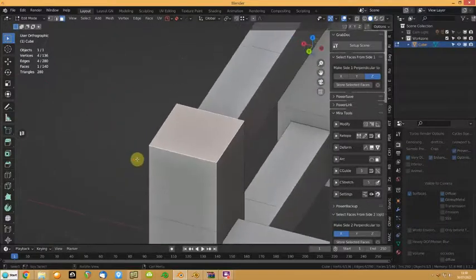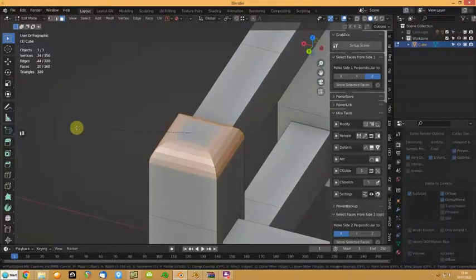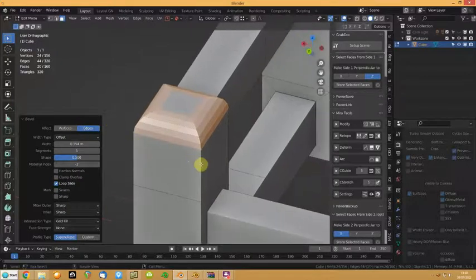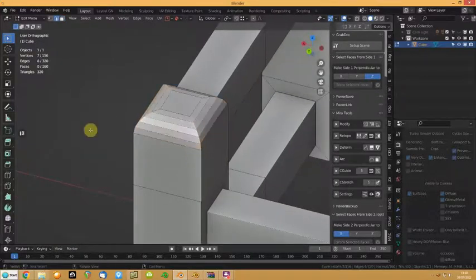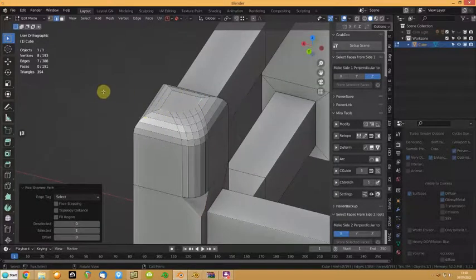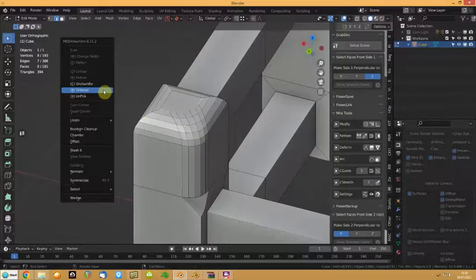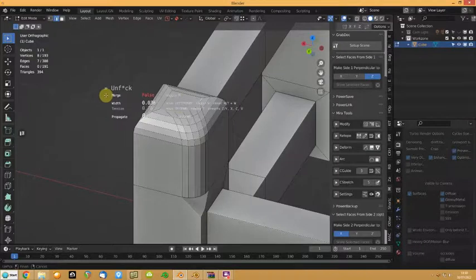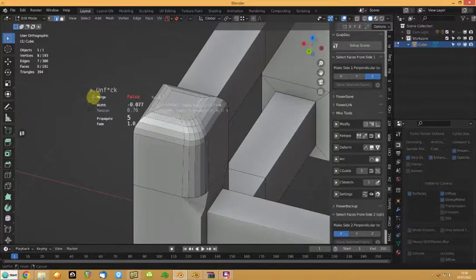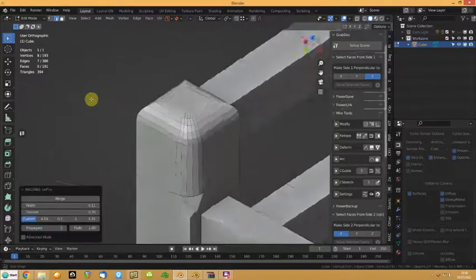Mesh Machine also has some wonderful bevel related actions. So like if we just select this, bevel it like that, and then I decide I don't like that, select that edge, control click that edge, go Y for Mesh Machine and choose that, and I can pull that in, then roll my mouse like that, that tidies that up.